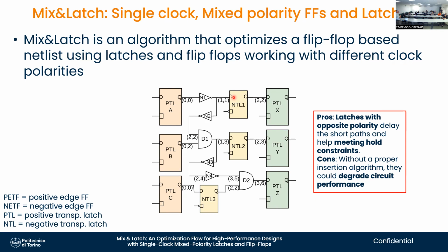And another quick question. Yes. You never insert buffers on the clock. You could delay the clock. Yes. Locally. Yes. Why are you not doing that? We are exploiting all of that. In fact, in the final layout phase, we are exploiting clock skew, smart clock skew, what's it called?